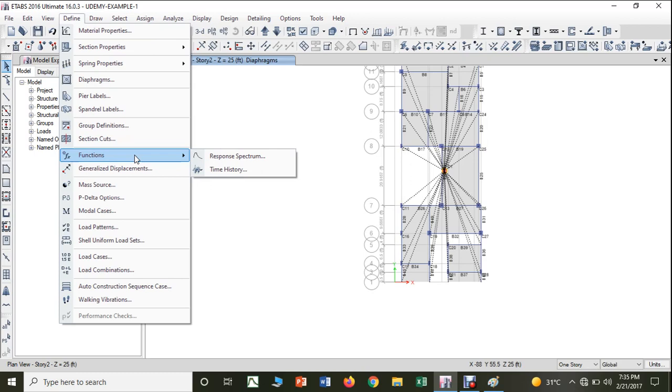Either the magnitude of the load may increase, the magnitude may decrease, or the magnitude may be the same but the direction may reverse, which may act left to right at the first second and change to right to left. Anything can happen. That's why the best example for dynamic loading is earthquake. Not only that, an earthquake will act on the particular structure for a particular interval of time. It will not act for an hour, it will act for seconds or minutes. So at that time there will be very large variations in the load.